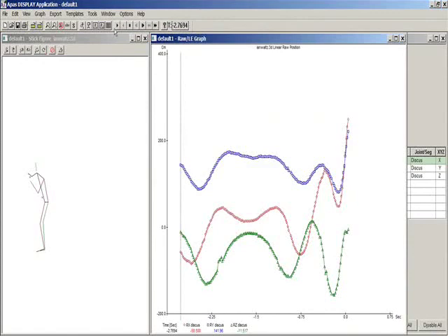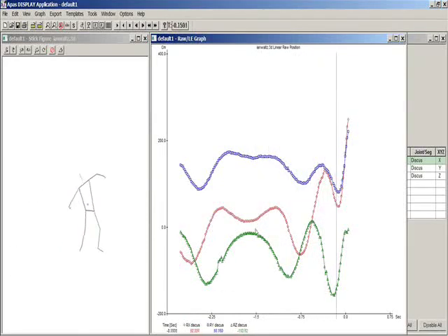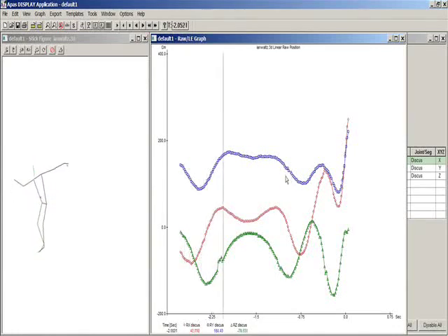And then if we let it go for every position here, you see that it's still jiggling. The reason is that it was not smooth. You also see in the data here that there are some digitizing errors. It's not very significant. However, we would like to filter the data first before we look for the results.